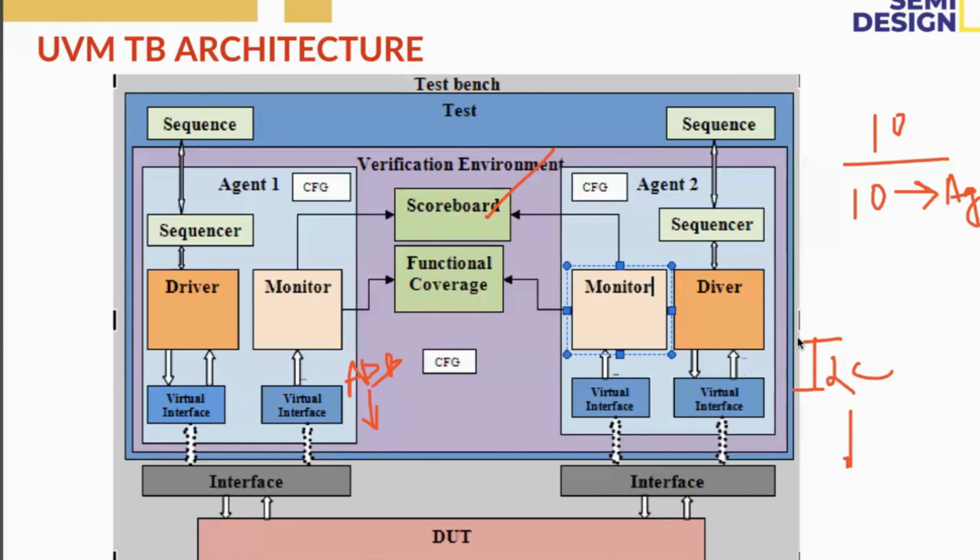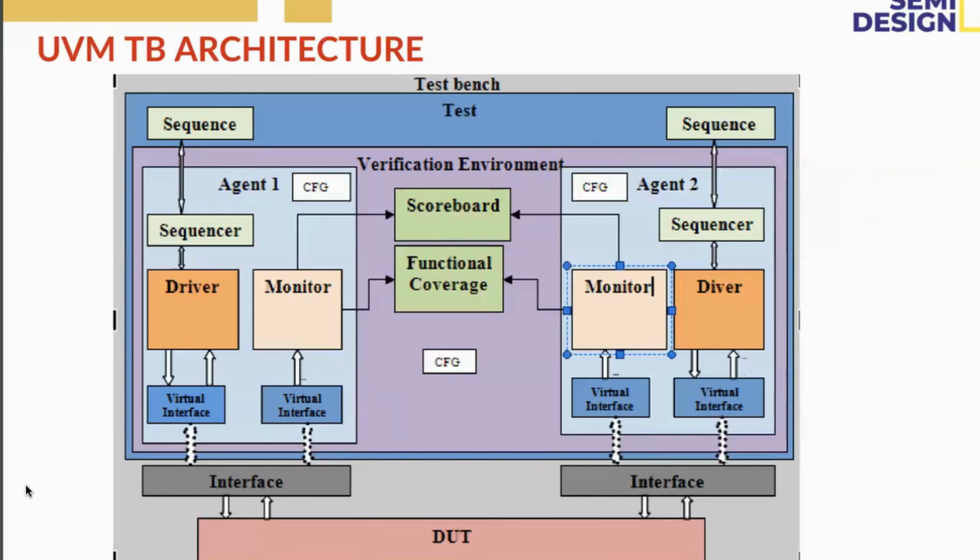Okay, can we have a scoreboard inside the agent? No, an agent has only three components: the sequencer, driver, and monitor. No, I have seen a subscriber or scoreboard used inside an agent. Maybe in SystemVerilog you have seen that in some cases, but here we are taking it commonly, right? That's why it is outside the agent. If you are taking it combined, you can put it in the agent only.